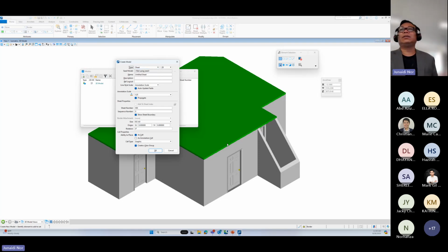for my paper space. I give a name to the sheet. Normally my title block is always A1, so I put an A1 title block there. Normally in AutoCAD you never put any name, you just leave it as layout. For me, I can create one A1 title block, A3, A4, A0. So I can create multiple title blocks. Scale is 1:1.